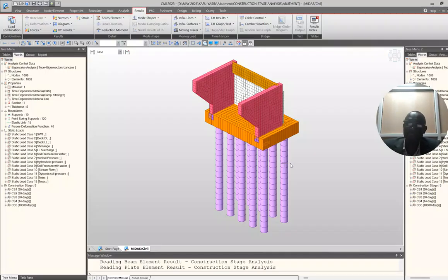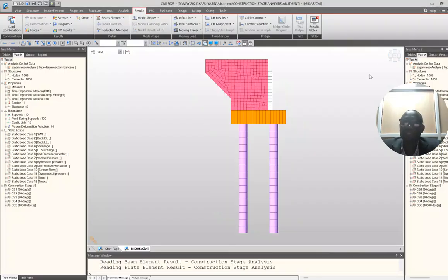Of course, this is a calculation from the hydrologist. It is about 13 meters is the pile length, then 3 into the rock, and the scour is about 12.6. So if you round up and then you get into the rock, you have about 16 meters. So definitely in the model, you have to ensure that this overburden soil between the pile cap all the way down to the bottom of the scour, which is top of the rock, is free.